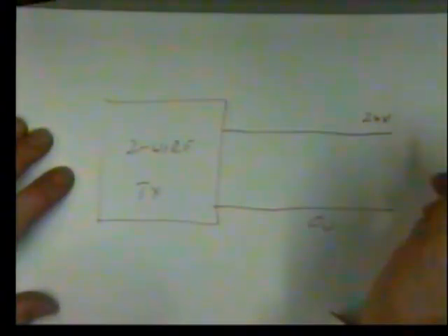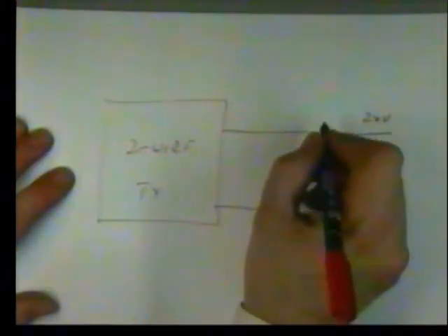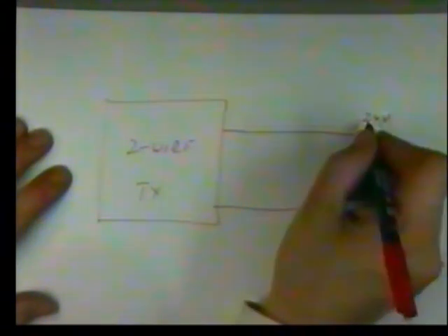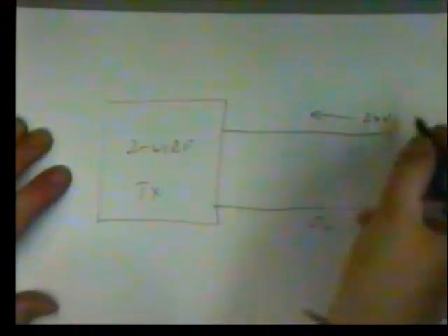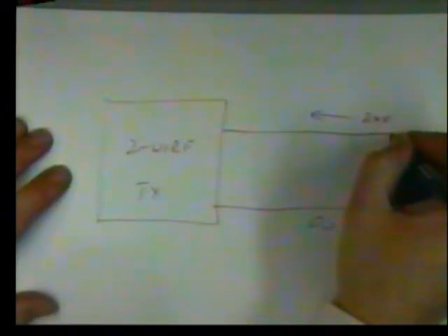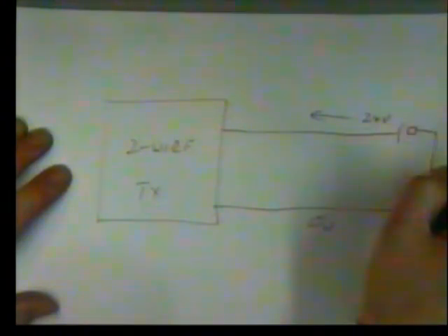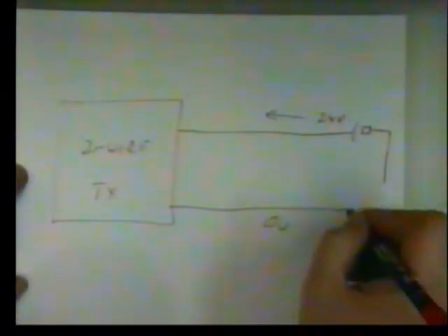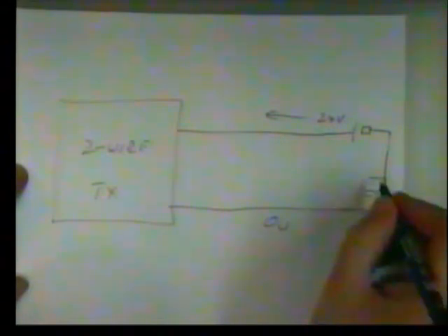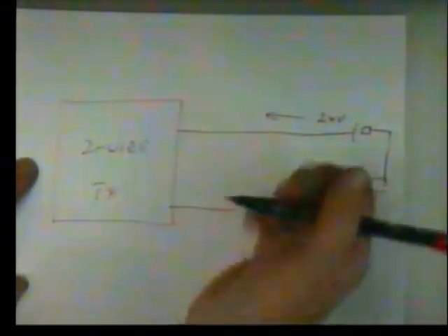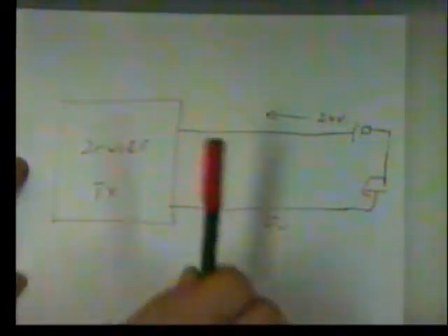If that is a fixed voltage, the way it's done is by the amount of current that is drawn. The current is a measure of the amount of power you're draining from the remote source. The 24 volt supply is just a dirty great big battery that is stored remotely in your control room, providing a 24 volt signal. What you vary is how much power you drag out of the battery.